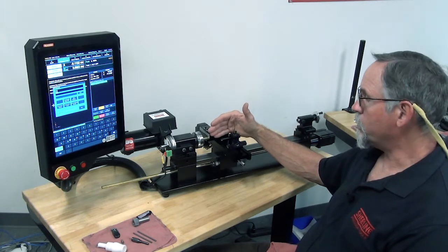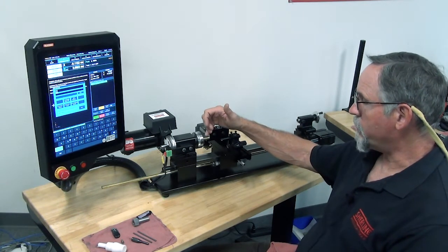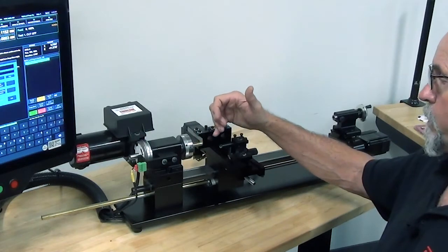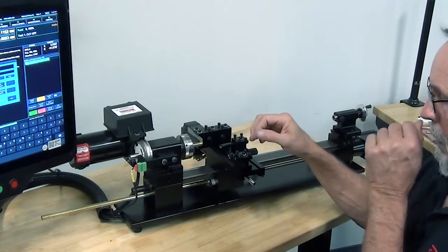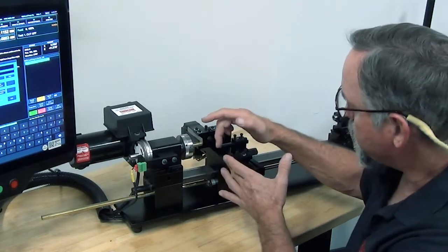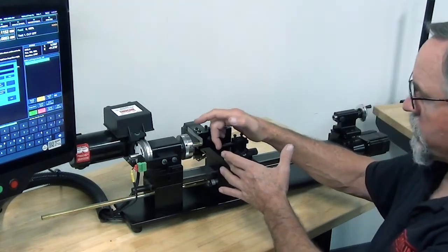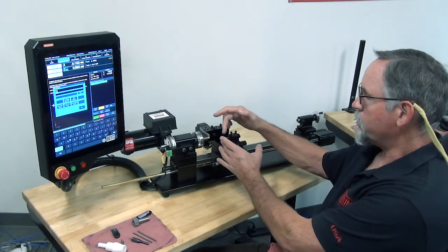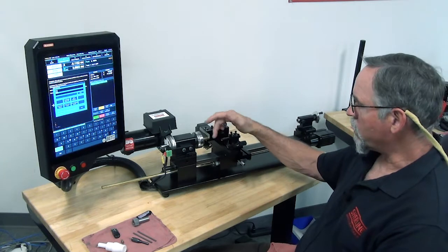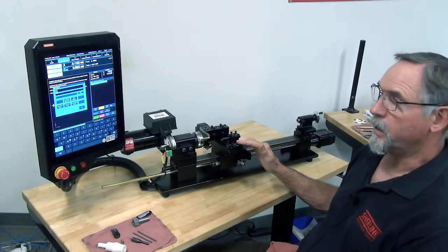Then for the next tool, I get done turning with this. He's on the back side. I move it out and I move it to 1 inch. Then again, I would call this tool up because it's almost the same as far as its Z location on the cross slide. Move my X into position, call up this tool, and then start working with this tool.